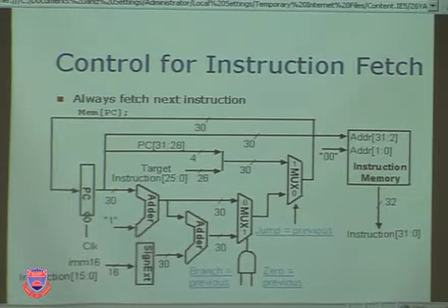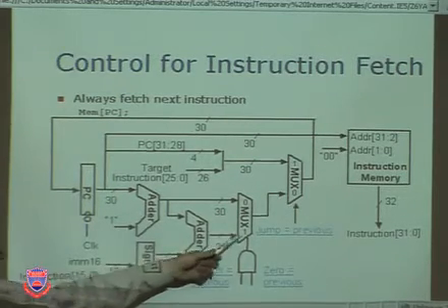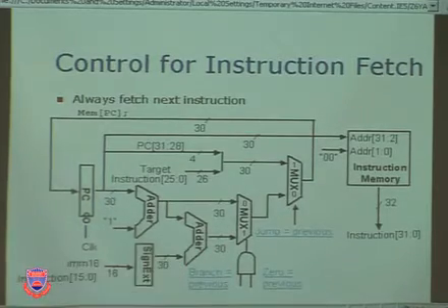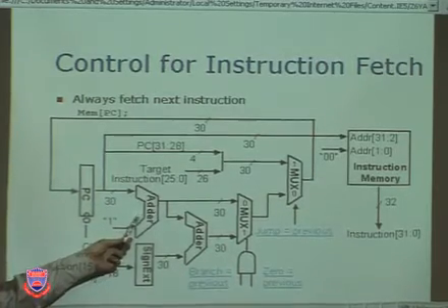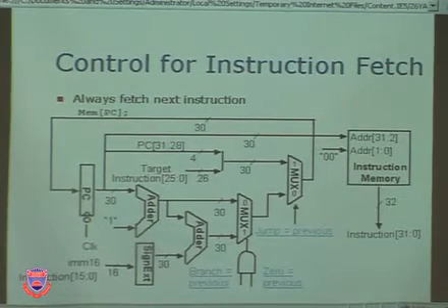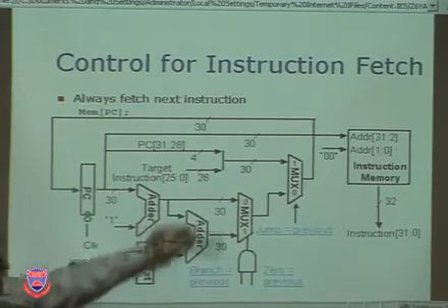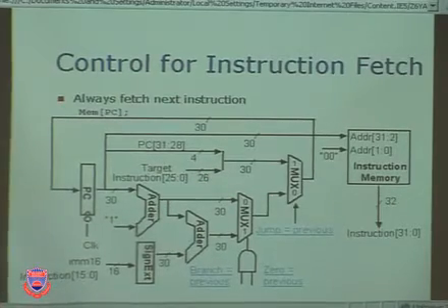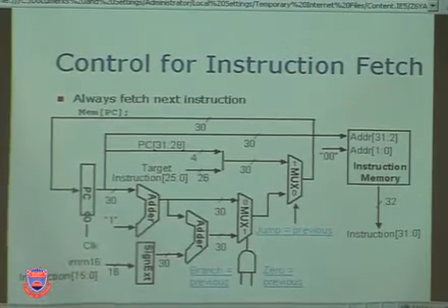There aren't any. But there are for controlling this mux, and there are for controlling this mux. This is an adder. It does the same thing all the time. This is an adder. It does the same thing all the time. If something does the same thing all the time, it needs no control. Control means sometimes do this, other times do that. You can see this mux chooses between these two. This mux chooses between these two. Okay, so those 3 signals are our values.